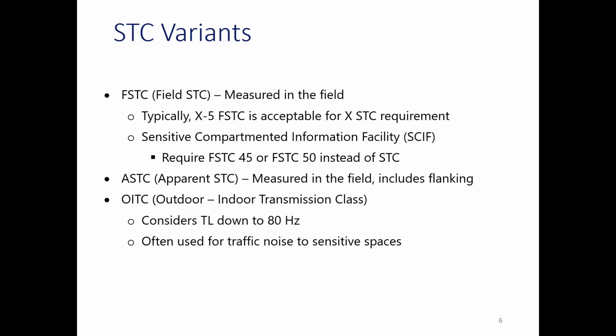The next one is the outdoor-indoor transmission class. So this one, remember we said the STC only goes down to 125. Well, this one goes down to 80 hertz. The point of this is they realized another shortcoming of STC was, besides not attenuating music and movies and stuff like that with a lot of low frequency content, it also didn't attenuate traffic noise very well, because traffic noise has a lot of low frequency content.